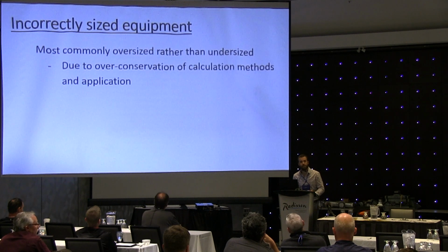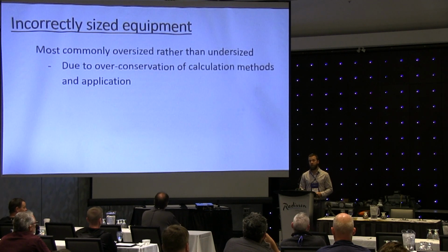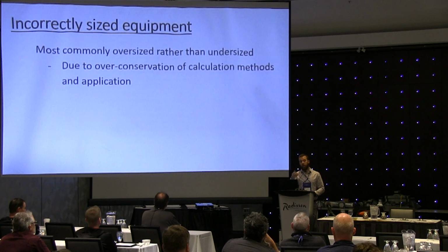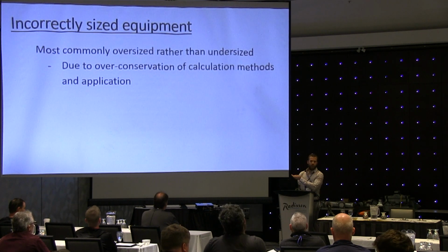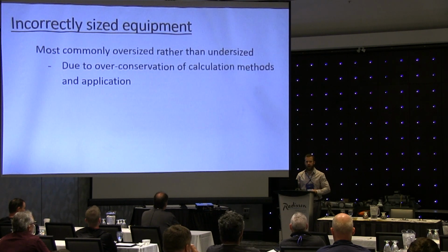What was that? Right. Awesome point. We've got all these improvements in construction. He's talking about the thermal resistance of a wall or of a window, maybe even your air tightness as well, ventilation system. Everything's changed now. So the BTU per square foot method, amongst many other reasons, should not be used anymore. Yeah, you have to actually consider what's in the house. Why bother putting better windows and better walls in if no one's been looking at that?